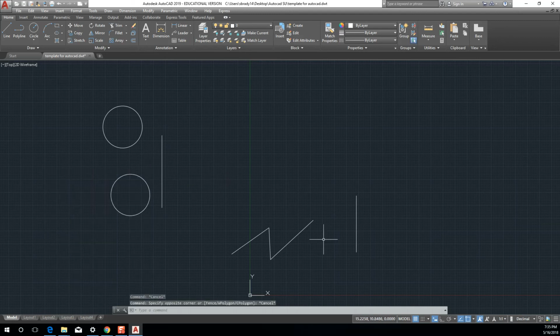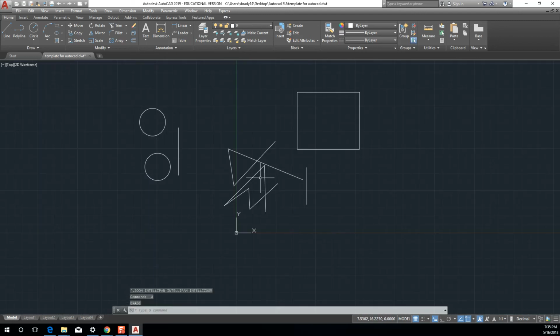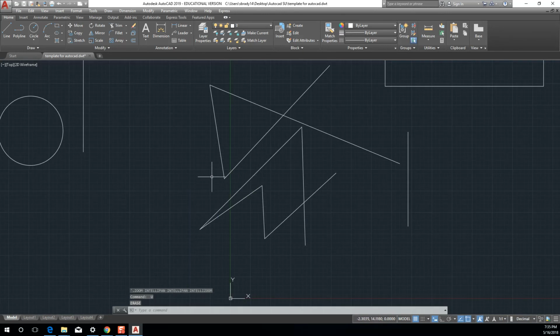So if I'm in a very confined space, which sounds really silly, but it happens in AutoCAD, where maybe I just want to get this line. If I come in here with the green selection window, I pick all 3 of those, right? There's no way around it. I could also use the blue selection window, click, and now I can very selectively pick just one object on my screen. Okay, so that's what the blue selection window is going to do. Any other questions for tonight?